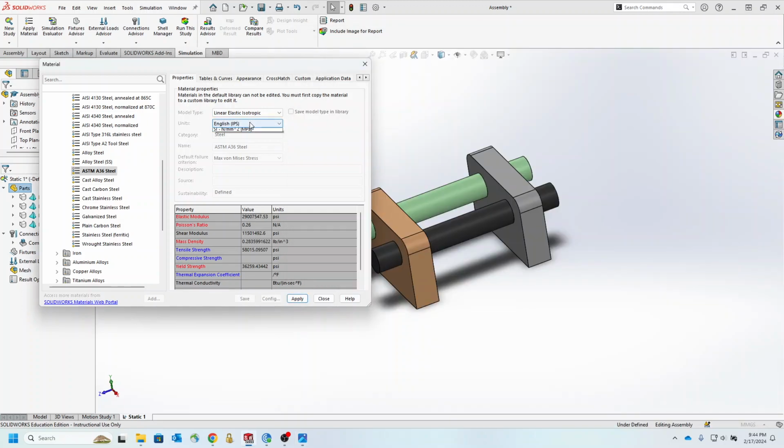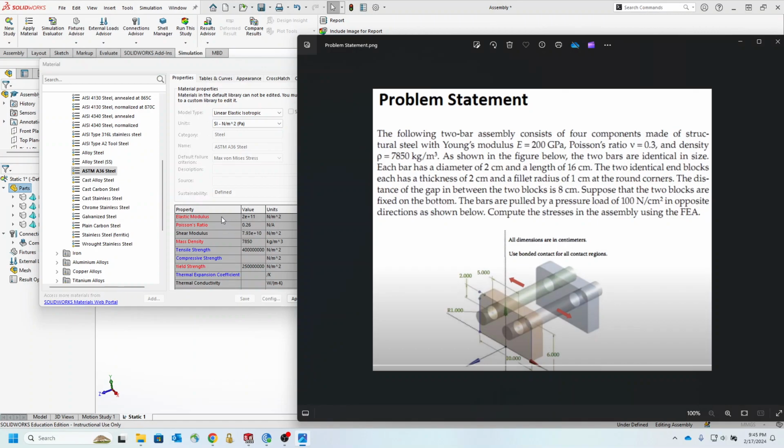So you're going to change the unit from here to SI. And you will see that the elastic modulus matches. It's 200 GPa. Actually, Pascal is equal to 1 Newton per meter square. So that matches. Poisson ratio is a little off. Density matches with this one, and the yield strength is the calculation of this, should be accurately here.